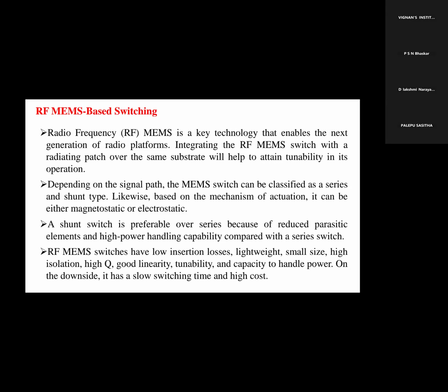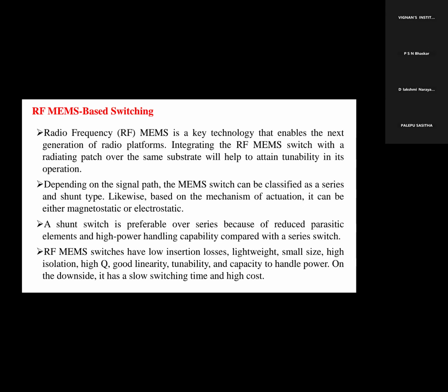RF MEMS switches have low insertion losses, are lightweight and small in size, and have high isolation, high quality factor, good linearity, tunability, and the ability to handle power. On the other side, they have low switching speed and also high cost. That is the main drawback in the case of RF MEMS switches.